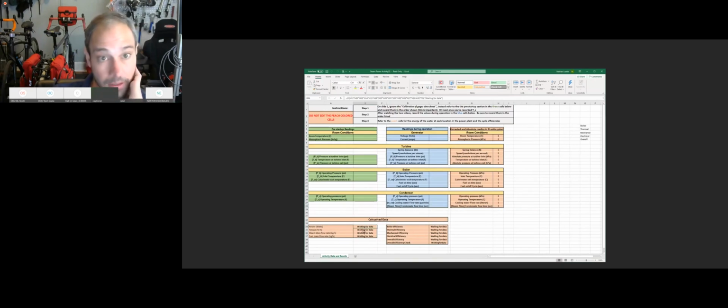Okay, so what is this stuff? Pre-startup readings. These are the readings that should be room temperature and 0 gauge pressure. Most of them are, not all of them are. These blue ones are the actual readings that you're going to take. And then over here are all of the corrections and unit conversions. Okay, so where does that come from?